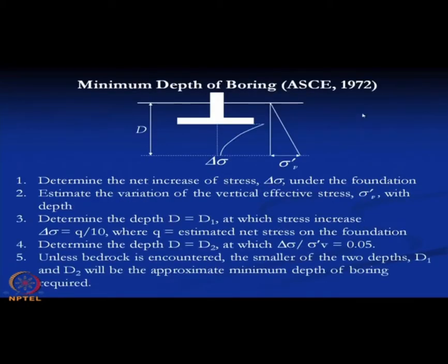Now, the depth of boreholes: what would be the minimum depth of boreholes? First we discussed the number of boreholes, then the spacing of boreholes, now the depth of borehole, up to what depth we will collect the soil sample. That is a very important issue. Generally the influence zone of a foundation is taken as twice the width of the foundation. That is a thumb rule, but there are some recommendations by which we can determine the minimum depth of boring.